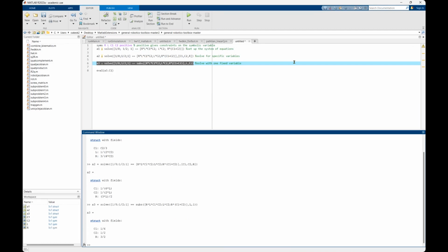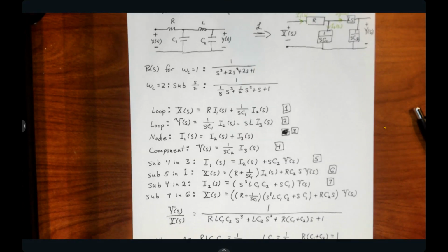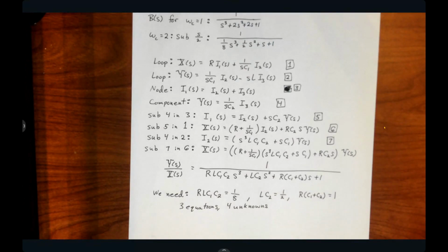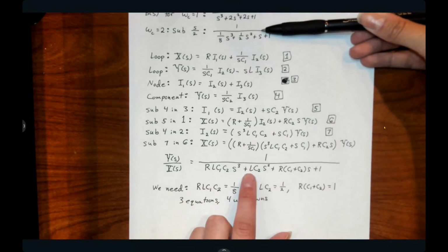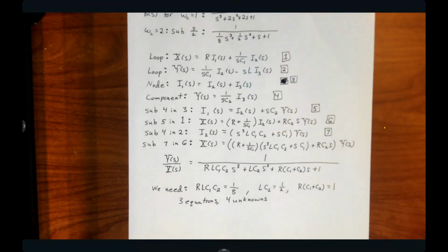Right, so a little bit of an aside there. And that pretty much wraps up then everything for Butterworth filters, right? So you might see in homework or exam this kind of idea of you have some circuit, gives you some specific form, and you want to figure out what is your low pass filter, potentially with an arbitrary cutoff. And then once you have this form and you have this form, then all it is a coefficient matching to figure out what values would I need for these components to get the type of low pass filter that I want.